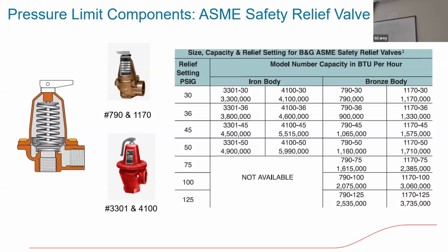The relief valves are a kind of combination. I'm going to have a maximum operating pressure that the equipment you've installed or specified says. The boiler manufacturer says, hey, I can't operate anything higher than 50 pounds on my boiler. That's when it got tested and proved. The other part of that equation is, in addition to honoring that max pressure, what's the BTU capacity? How much heat can this thing develop?